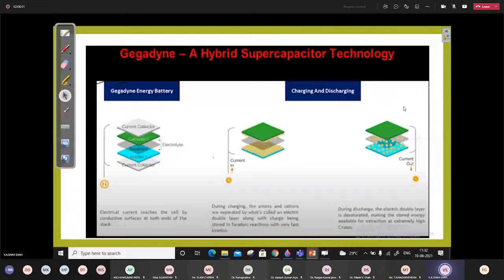The reason is that these two are connected in parallel, so the supercapacitor voltage will float with the battery voltage, and the battery will supply power to the system as well as charge the supercapacitor. So the disadvantage is that the supercapacitor terminal voltage continuously varies with load variation and voltage variation at the DC link. So UC energy is ineffectively used. We are not able to use the complete energy available in the UC.